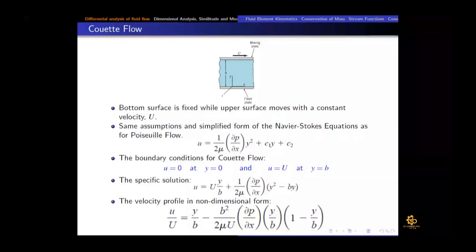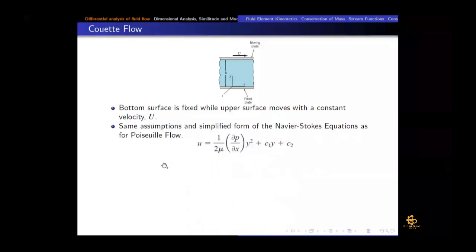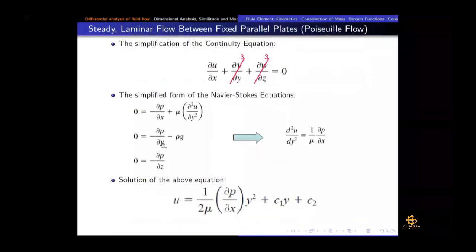It is the case when the flow goes through certain turbomachinery applications, or flow over an aeroplane, or flow over a vehicle. In those cases, we cannot get these velocity profiles which are being obtained by converting the Navier-Stokes equation into an ordinary differential equation.